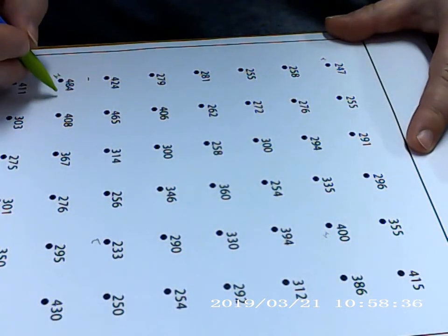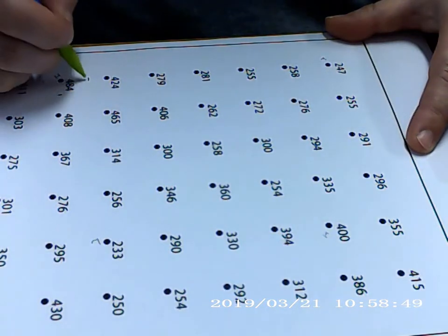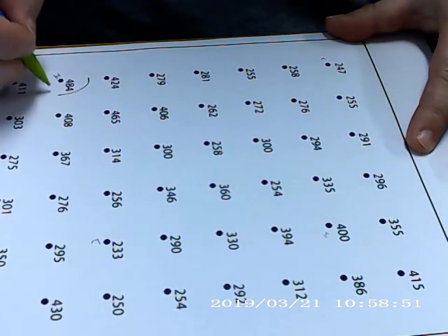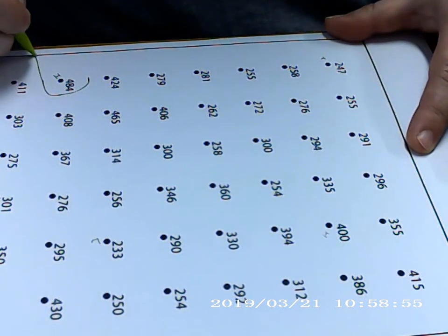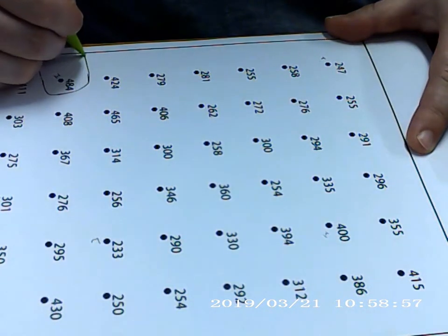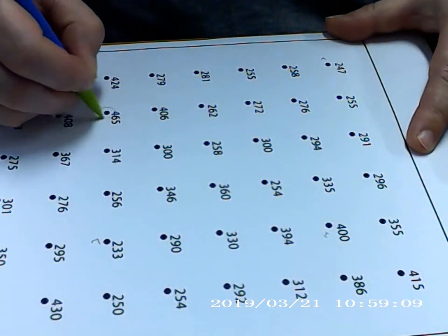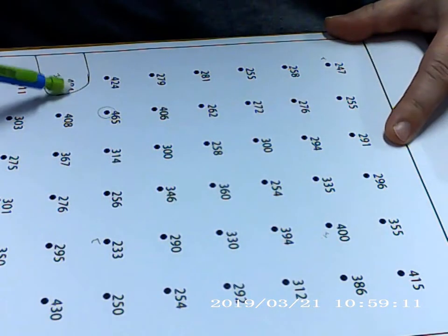The highest value is 484, so our first contour will be 450 metres. We can draw our 450 metre contour around our highest point. Our contour must either close or extend to the edge of the map. I have chosen the latter option here. But, oh no, I have made a mistake.